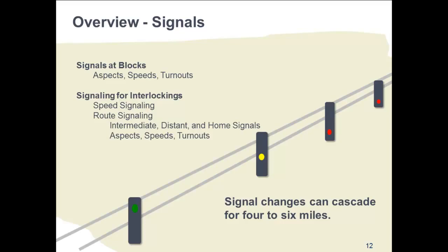It is important for grantees to understand the basics of signaling. Many passenger rail projects, as part of their scope, are replacing 1920-era signaling with modern signal technology. So learning the basics will help people to insert new signal segments in an optimal way. To give an example, a passing track or universal crossover is being inserted in the main line. Ideally, if new interlockings like these are being inserted, they should be located at existing signal sites in order to minimize disruptions to the existing signal system.